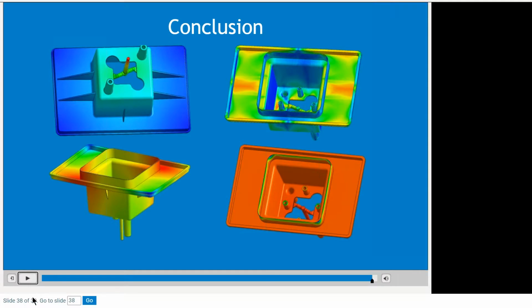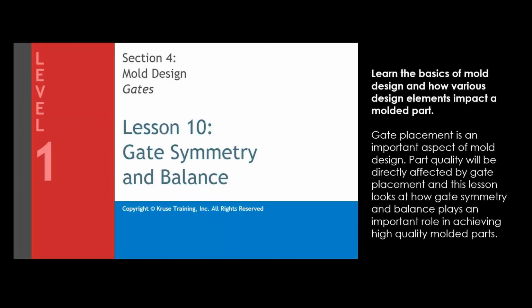it is important to look at the overall behavior from filling, the distribution of the pressure, the fiber orientation, the packing pressure distribution. All of that will impact the part final shrinkage and warpage behavior. Doing this up front, of course, is easier than after the first mold is built and the wrong gate location has been chosen. So I can only encourage you to learn, to evaluate, to optimize, and then go into the production of a part after the part design is optimized.